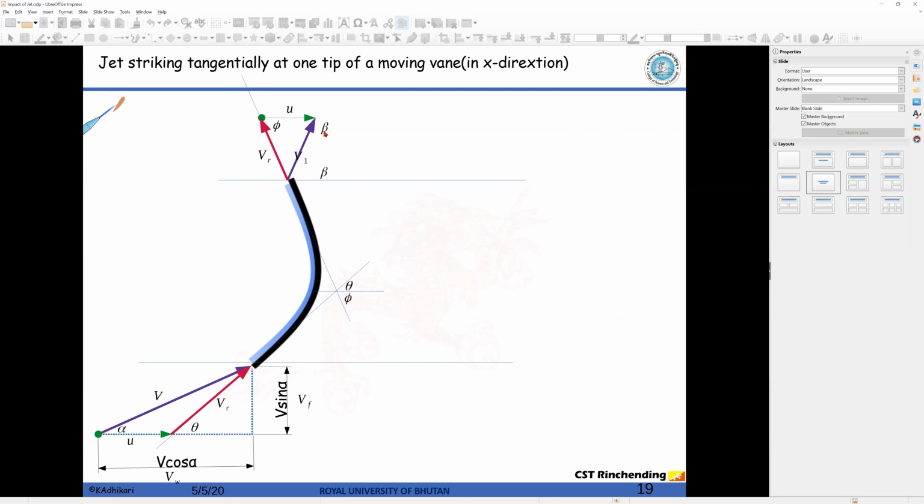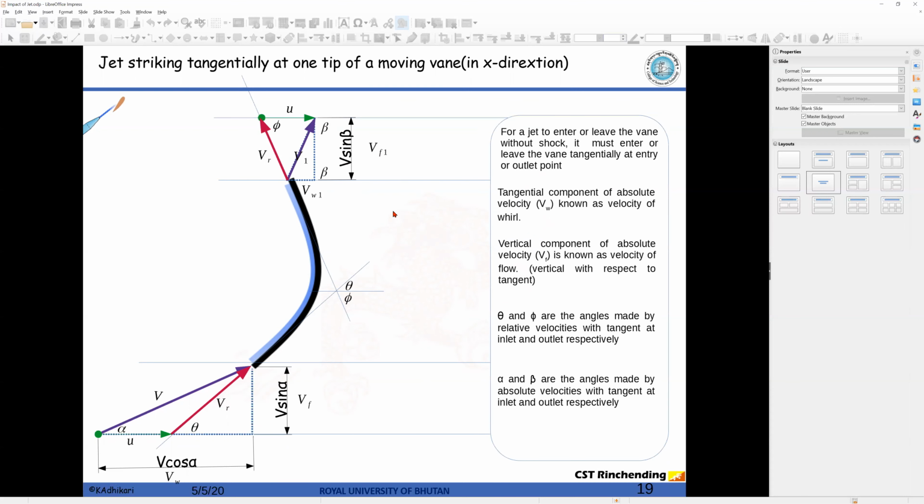All right, so let's say this is the beta. So I was talking about the beta, and likewise we can find the x and y component of v1 absolute velocity. This is the velocity of flow at outlet, velocity of wheel at inlet. This is pretty much what you need to understand from a velocity triangle perspective to solve this problem. Okay, so at this inlet and outlet, most of the parameters remain the same, direction, everything remains the same except for this v1. If v1 is obtuse, the orientation will be like this. If v1 is acute, then it will be something like this.